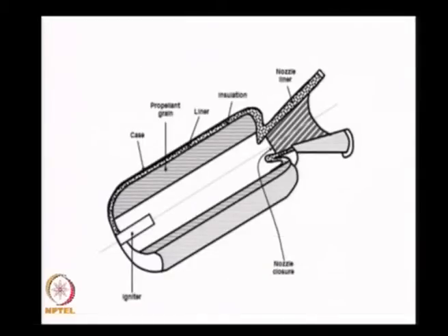Now, having done all this, let us put everything together in a single diagram. What are the components of a solid propellant rocket? Well, propellant, basic. It is contained in an insulation or a liner. Then after this insulation I have another liner. Make sure that it is compatible with this insulation such that when the motor burns, the heat does not allow the motor case, which is a metal, to burn off. Therefore, I have a propellant, I have a case, I have insulation, and liner is also a form of insulation.